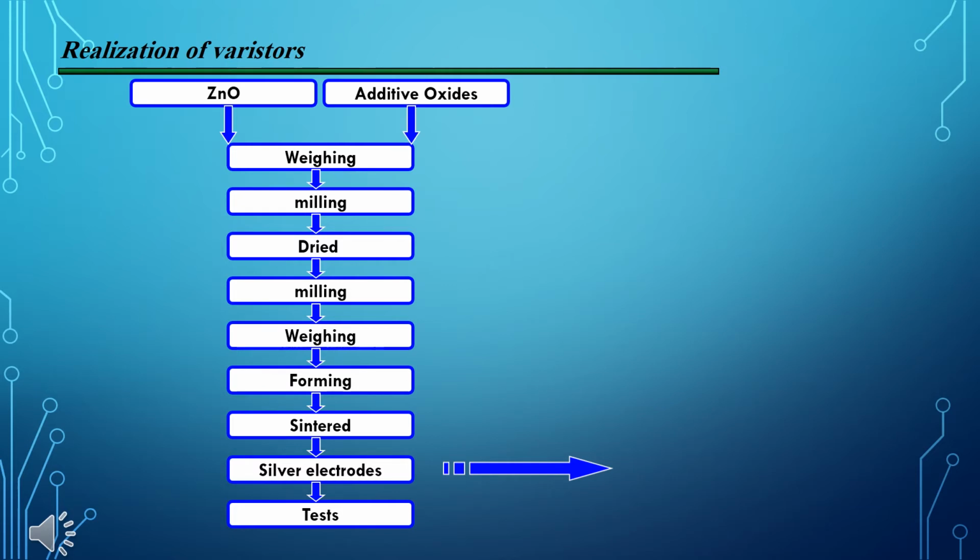Secondly, the Zn-based varistor sample with the nominal composition shown in this table was prepared by the traditional ceramics method. Raw materials were mixed by ball milling with zirconia balls and ethanol in a polypropylene bottle for 24 hours. The mixture was dried at 120 degrees Celsius for 12 hours and calcined in air at 750 degrees Celsius for 2 hours. The calcined mixture was pulverized to produce the starting powder.